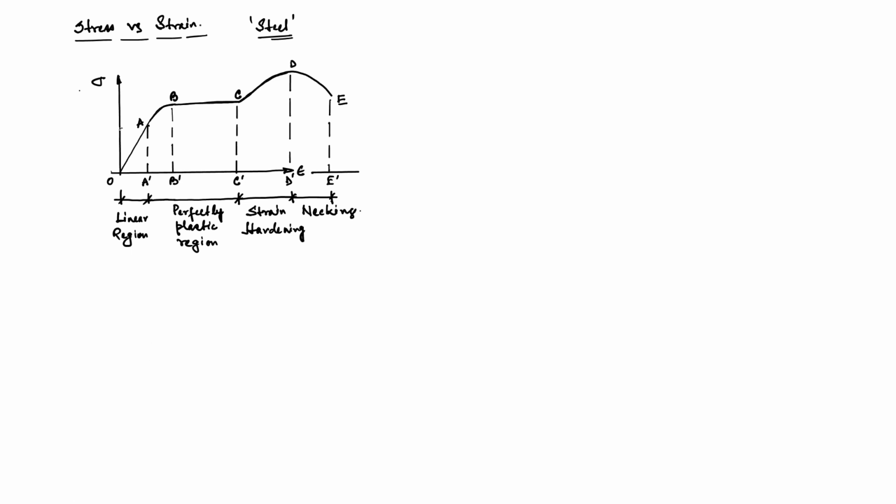Now, if we draw the horizontal lines at this point, we get different stress points. So, this is the proportional limit. Why is it called proportional limit? Because up to this point stress is proportional to strain. So, if we apply a force, the body will deform following this path, and if we go for unloading, it will again come back to 0.